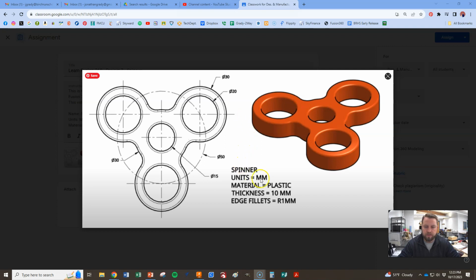It's in millimeters, all stuff good to pay attention to. And then, obviously this is probably where we're thinking for the origin. It's right here on that. And so having said that, what we'll do then is create this center hole, circle at 15 diameters. Then it's got another circle in here at 30 diameters, even though it's kind of hard to see. So 15 and 30, origin in the middle, millimeters.